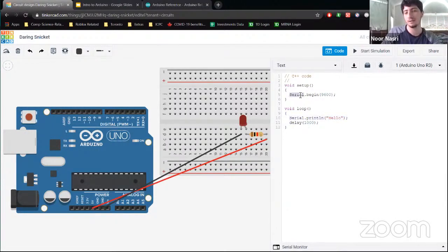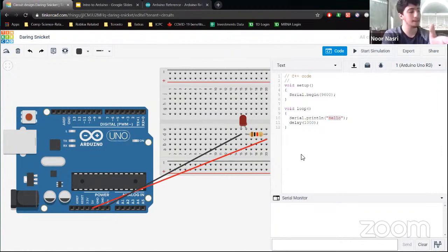So this line is just somewhere you can put anywhere you want. As long as you've already started, it knows that it's going to be talking on 9600. Then it's going to send this message. Okay. And then serial monitor is going to track that message for you. So this looks like it's together, but in reality, the code is going to be on the Arduino, and it's going to be doing something. The Arduino is going to send it at that rate, and you're plugged into the computer, which is going to read it, which is why it's useful.